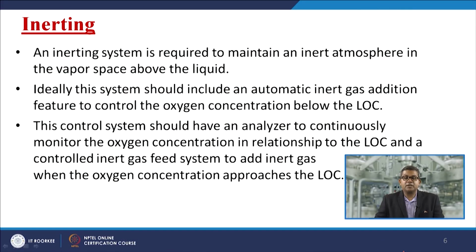An inerting system is required to maintain an inert atmosphere in the vapor space above the liquid. Suppose I am working with a pool of, say, hexane, and just because of its vapor pressure, a certain quantity of vapors is generated just above the liquid surface.